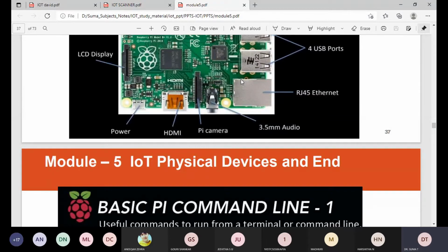The video output we get is through the high definition multimedia interface or composite, and it has an LCD display. The display ranges from 640 by 350 to 1920 by 1200, including 1080 pixel, PAL or NTSC standard. The power source is a micro USB. You can see next to the LCD display, down below, the power jack is there, where you are going to connect the power.